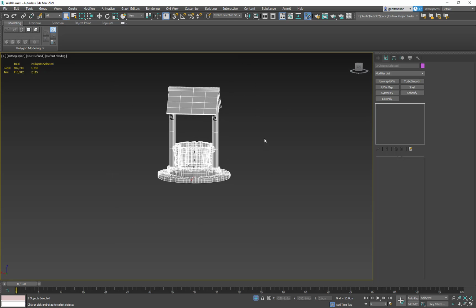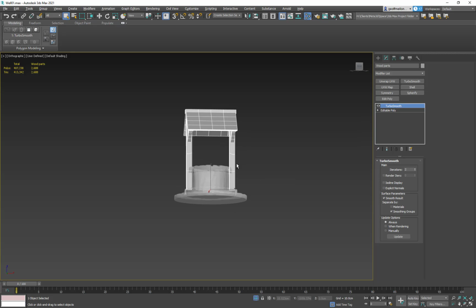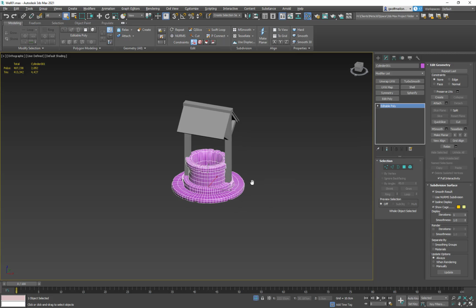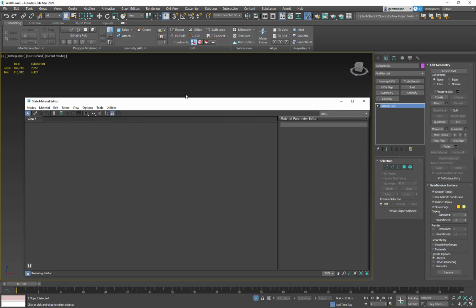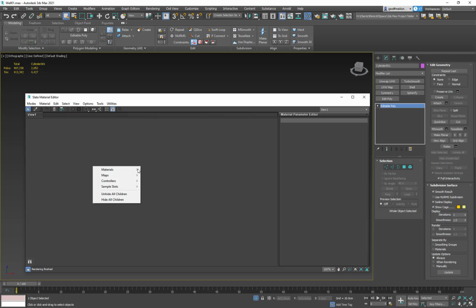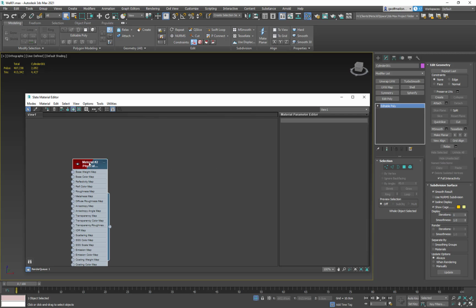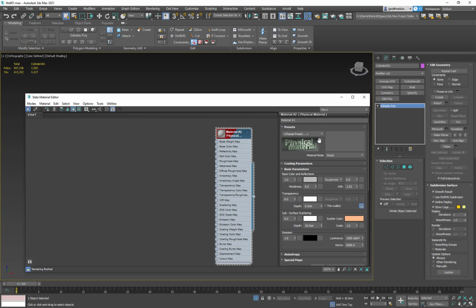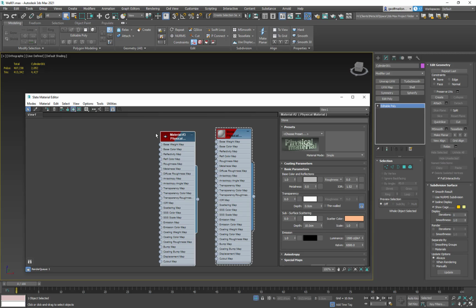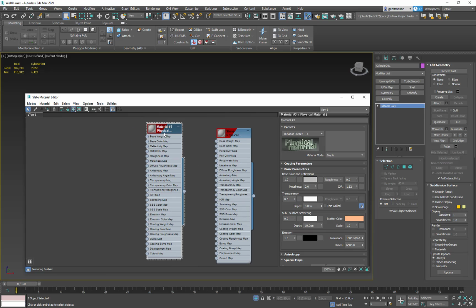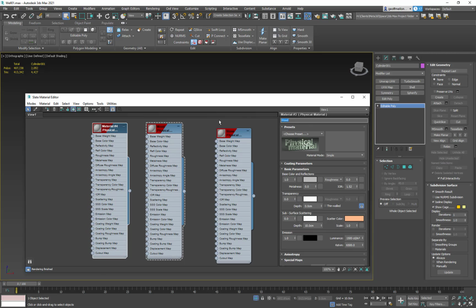And when you bring stuff into Substance from Max, the way we've done it differently here, what you want to do is go to Materials inside of Max. And you want to make a material. We're going to double click on this, it'll show up over here. We're going to name this Stone. And then we're going to shift and drag a copy of it. I'm not really worried about the textures. The important thing about these materials is their names. And then Wood, if you want to do that. And then you could do another one that says like Metal.